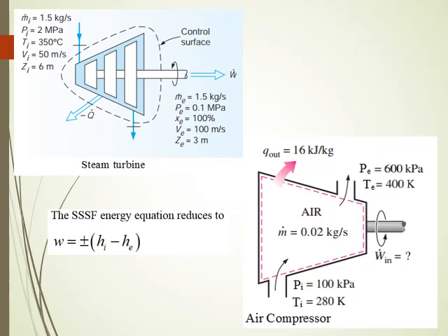It is a similar sign convention to that in the heat exchanger. In heat exchangers we had the heat transfer rate equal to plus or minus (He - Hi), where plus stood for the boiler or evaporator and negative for the condenser. Similarly, I have put both signs here: positive stands for the steam turbine and negative stands for the compressor.